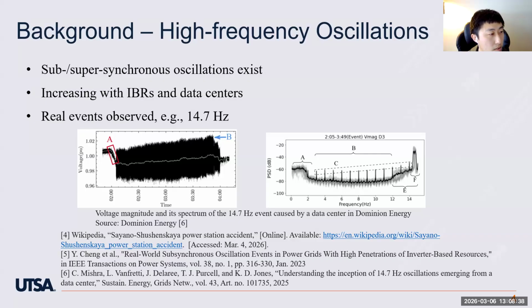But nowadays, subsynchronous oscillations are emerging from increasing inverter-based resources and data centers. For example, the 23 Hertz large load oscillations in ERCOT and the 18 to 20 Hertz oscillation from Kauai Island. The second reference on this page is a technical paper by the IEEE IBR SSO task force summarizing the real-world SSO events.